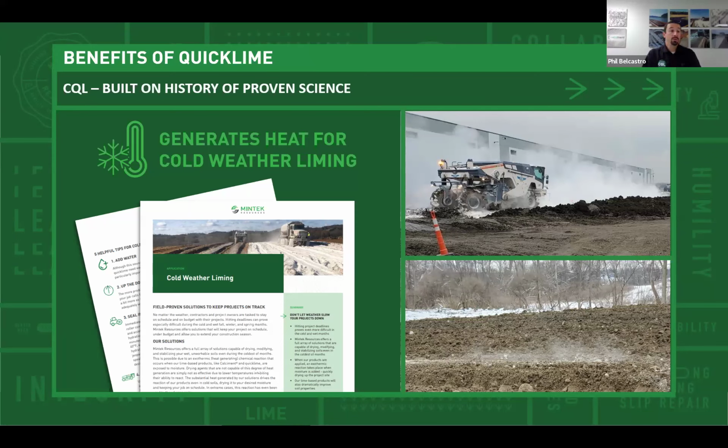Maybe you're not quite the believer for some reason in lime yet. Let us get out there. We can dry that soil. We can generate some heat with the lime. If it's the clay soil, maybe we can prove to you that lime really is the answer. Happy to do some of that testing here at the Innovation Center. But that extra heat, we can allow the cement stabilized soils to cure as they would in warmer conditions. Especially when we're working in lifts, we have that nice warm blanket of soil on top, insulating it.